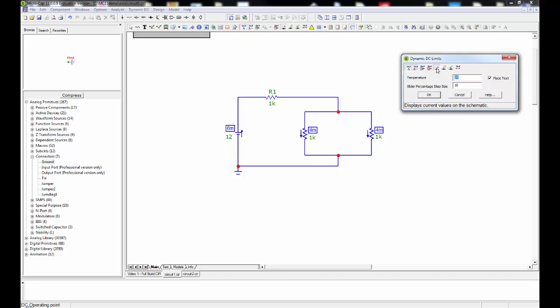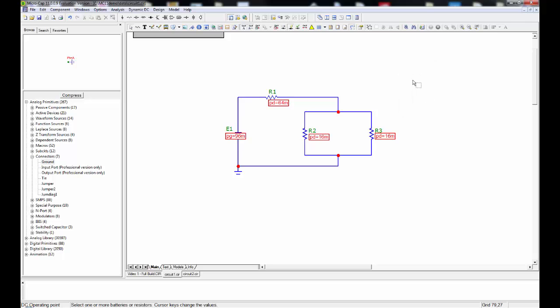Okay, if I move over and turn the current off so I don't clutter the diagram, again move to the right, and this little bolt of lightning on there is for powers, so click on that and it's actually giving me the powers in the circuit. So PD, power dissipation, equals 64 milliwatts in R1. If I want to move these things around, I can do. First thing I need to do is get rid of the dialog box, which was active, so now I'm able to move the powers around, which is useful for assignments.